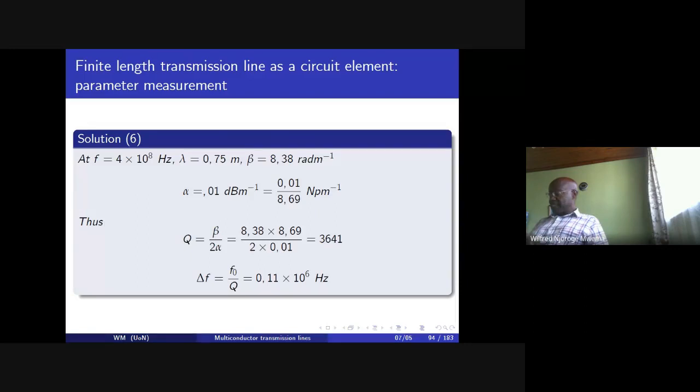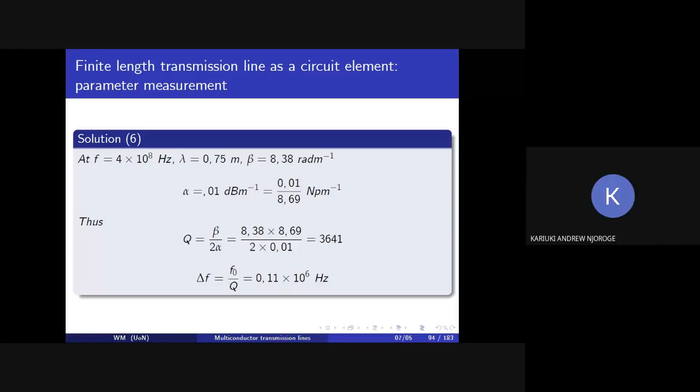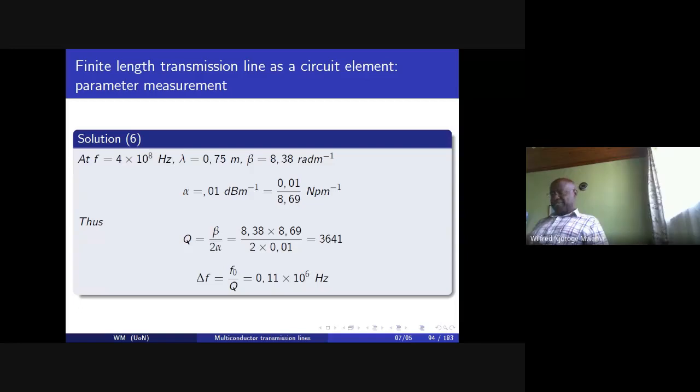Did you make oscillators? Did you study oscillators? Yes. It can be used as a resonator for an oscillator. Two, when you are making, say, something like a notch filter that filters at a single frequency, you want to make the bandwidth as narrow as possible, and therefore this circuit would be very possible to get that.